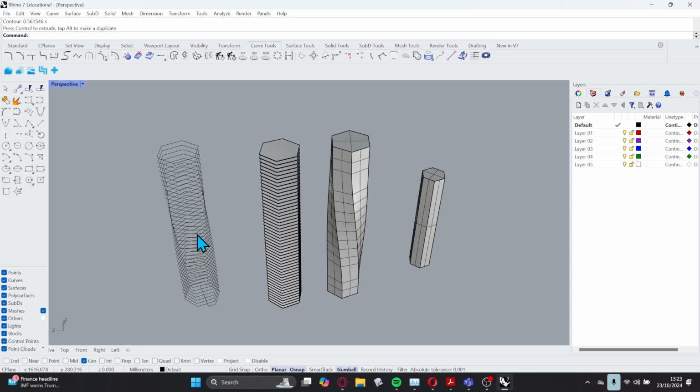Yeah. Snap to the center. If it's not letting you snap to the center, you need to make sure that your object snaps are on. This is where it's going to snap, and make sure the center is on. That should be. Yeah. So go back. Click on disable for a second.